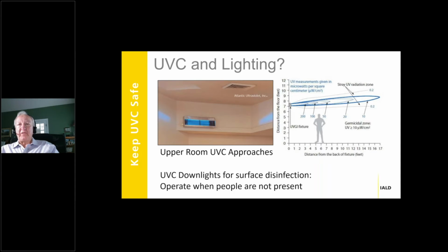Now, this is where the far UVC at 222 nanometers is gaining attention, because at this particular wavelength, studies are showing now that it may in fact be skin safe and eye safe, because at that wavelength, the radiation does not penetrate the dead skin cells in your tissue, and it doesn't penetrate the surface layers of moisture and cells in the cornea. But these studies are ongoing. Most of them have not been done on humans, although there are some human studies that have been published recently. And more importantly, the long-term impact of 222 nanometer radiation on people and materials in the built environment has not been studied. So it's going to take some time to really figure out how safe 222 nanometer radiation is for building into full-time disinfection in the built environment where people are present.